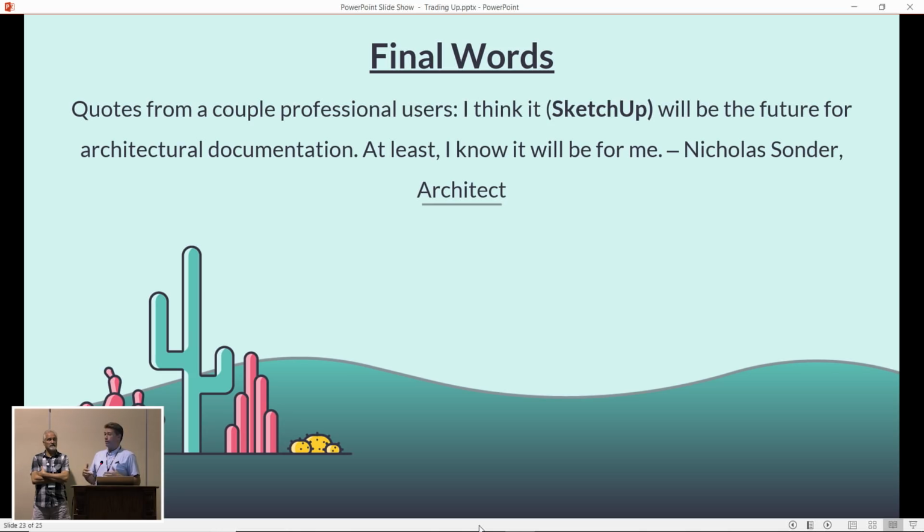Now, what they do get, when you open it up in AutoCAD, is the raster viewport that I have, which shows all the pretty textures. That comes out as actually a raster image, kind of pasted on the sheet. But anything that's vector line work, like a floor plan or section cuts, which is what they're looking for, all of that is vector line work. Plus they get all the text, which is nice.